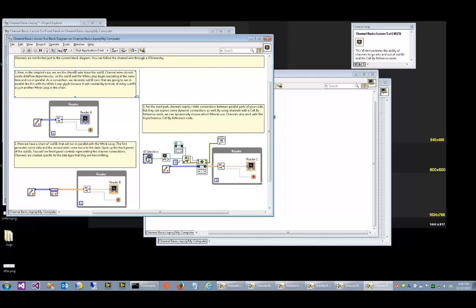We've got a coding convention that we've started. If we create a sub-VI with a channel endpoint, we put the while loop glyph on the icon. It makes it a lot easier to read these things and consciously remember, oh, that's a loop. There's an entire loop in there. That's a parallel chunk of code. There's been some people who've complained that they're used to seeing parallel code stacked vertically instead of going horizontally. The only people who think of it as horizontal are the FPGA people who are used to pipelining. The rest of us aren't used to that.